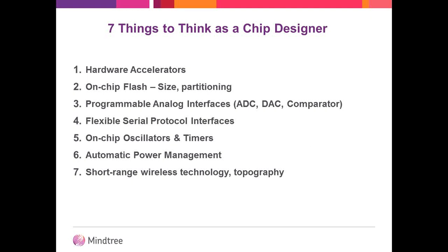The second thing that you need to consider is what amount of on-chip flash you are bringing in. The size is important in terms of how much data you need to store and how much data you need to process. You may need to determine the size, but partitioning is also important, as you may have different areas depending on your security requirements, depending on what kind of data you're collecting, what kind of data you want to expose, and what data you don't want users to write. You may also have to look at how you want to partition your flash, which is on chip.